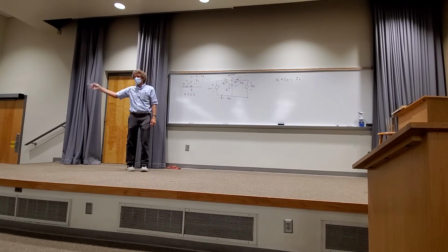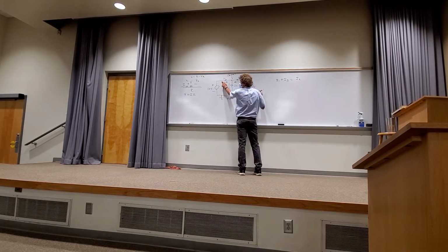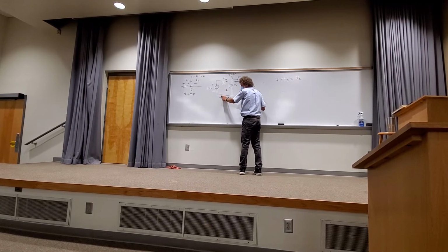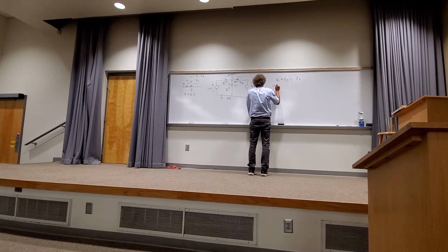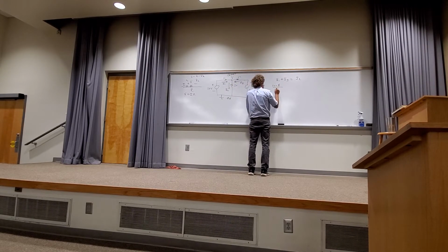All right. So when I come here, I1 would be the voltage on this side, measured with respect to ground, so that's 10 volts, isn't it? Take a look, that's 0, that's an increase of 10. So it'd be 10 minus the voltage on this side, which is V. Just V. Over R1. I made it a value, 10.